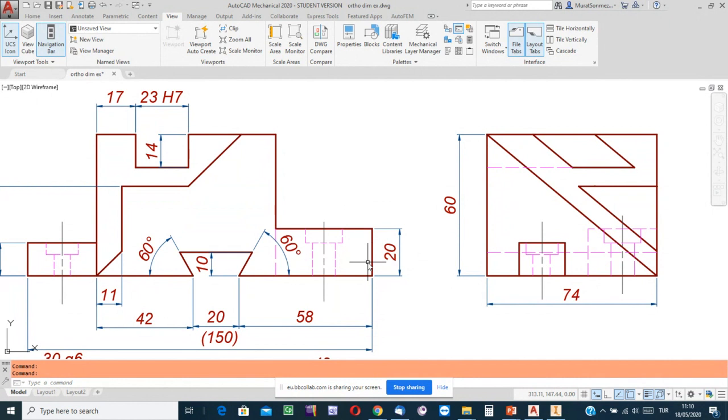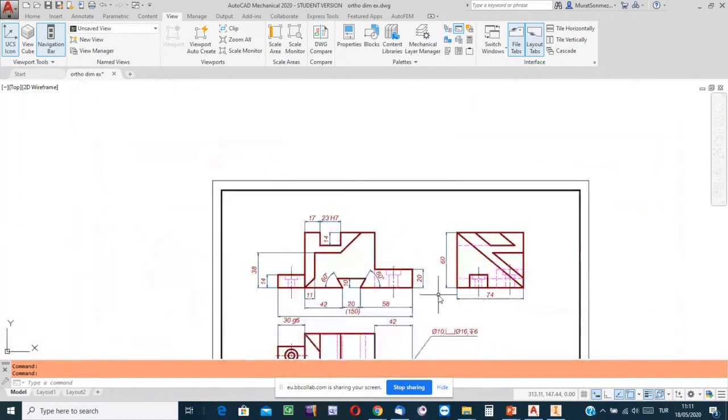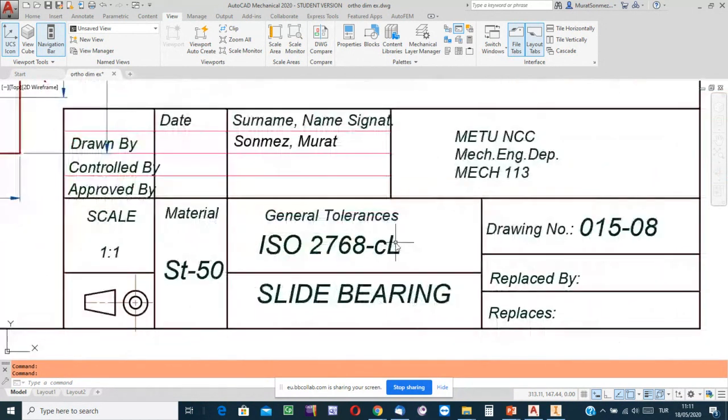So as I said in the second video record, one more time saying, for each dimension we need to inform the technicians on the upper and lower limits. For functional dimensions, we use IT tolerance grades today. For non-functional dimensions, tolerance class definition. At the title block, within the box, it is to be entitled with the phrase general tolerance, while using standard letters: lowercase letters for the size tolerance, capital letters for geometrical tolerances.